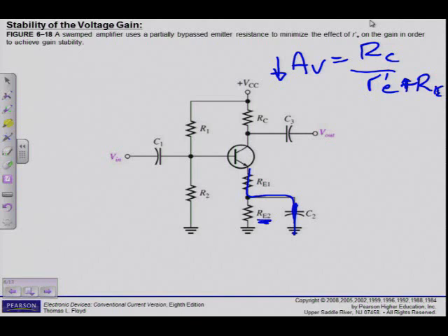So what am I doing? I am increasing my voltage gain again by making the value of RE half of what it was. Okay, so what am I doing? Remember, R'E is unstable, a very small resistance, but with a big resistor, no problem. Voltage gain is stable, but that big resistor is too big.